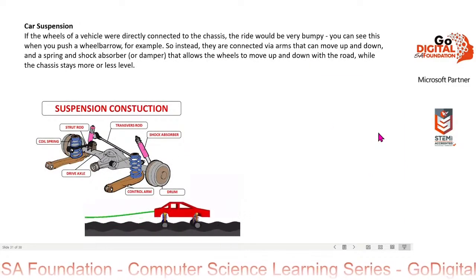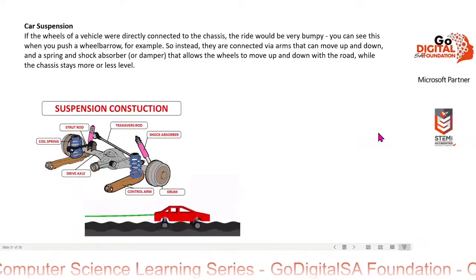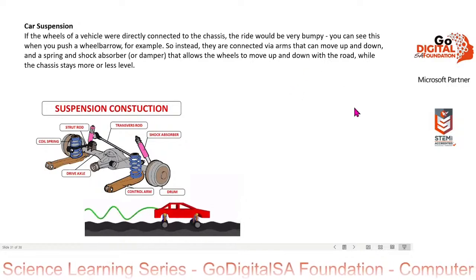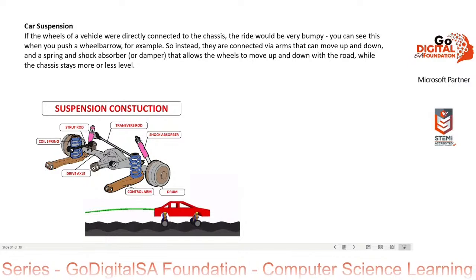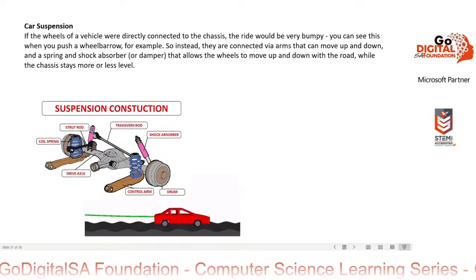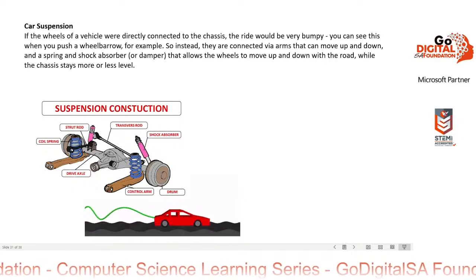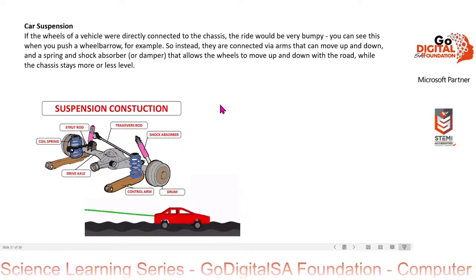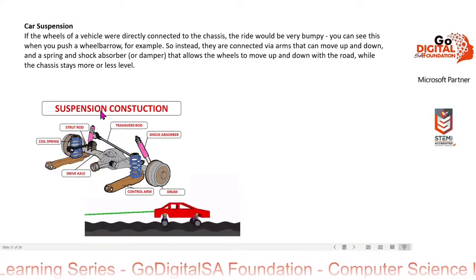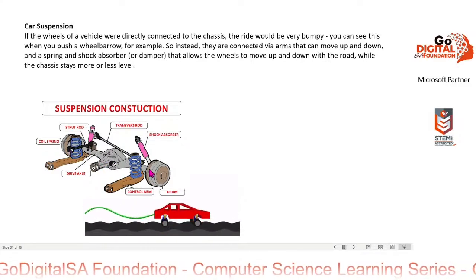Car suspension. If the wheels of a vehicle were directly connected to the chassis, the ride would be very bumpy. You can see this when you push a wheelbarrow, for example. So instead, they are connected via arms that can move up and down, and a spring and shock absorber, or damper, that allows the wheels to move up and down with the road while the chassis stays more or less level.